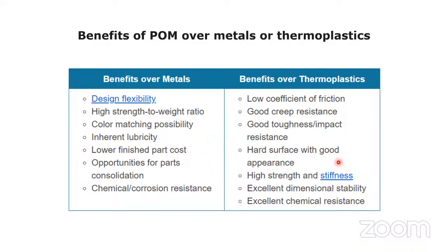They just heat it with a heating gun, thermal welding only. So in that case you can use thermal welding, but here, as you have mentioned, laser welding is possible in case of polyoxymethylene.